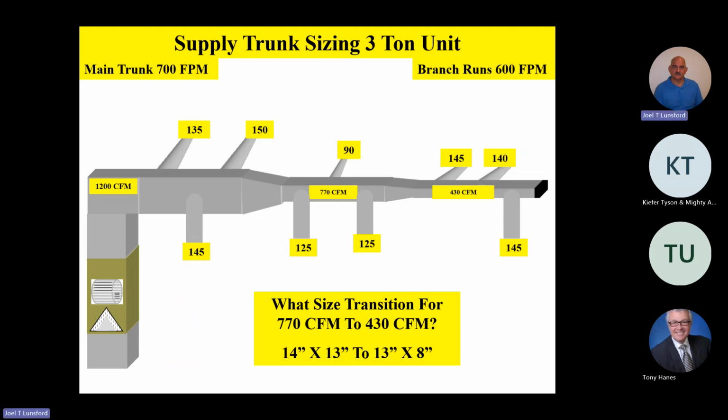And so that's very, very good duct practice, as long as you've got room to do it: stretch that main trunk out, that last main trunk component out, cap it, and then back off a couple of feet on that last takeoff. Now remember, team, you're going to have dampers on each takeoff, and so you'll be able to balance the airflow very, very nicely.